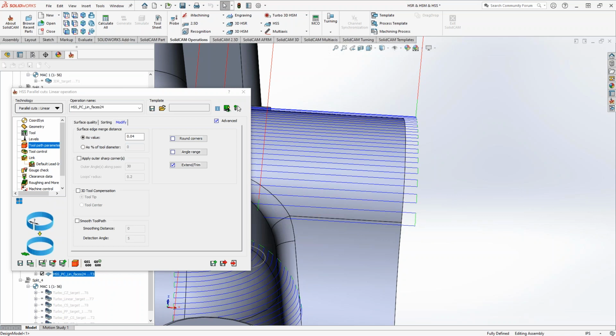This can also give you the ability to get almost intermittent lead in, lead out, because it's off the part. So if it does a direct move or anything like that when it links the slices, then sometimes that's a little cleaner than if you try to manipulate the link section to get lead in, lead out as it goes in and out of the part. So that's another way to lead off the part and do whatever you need to do to reposition it. Now, that's just extension.